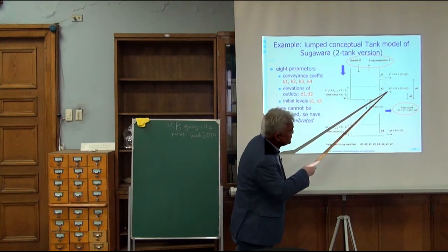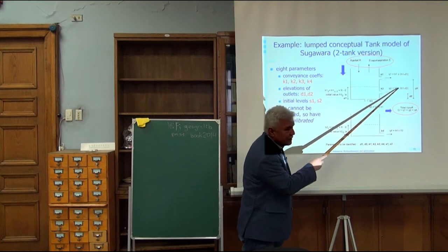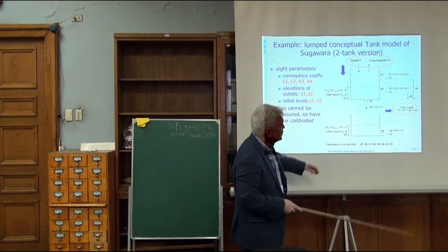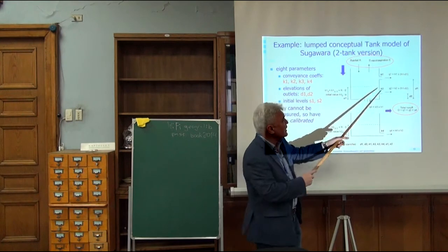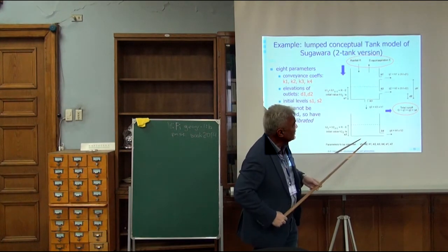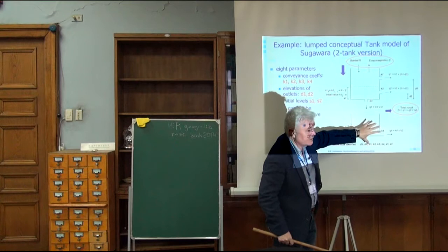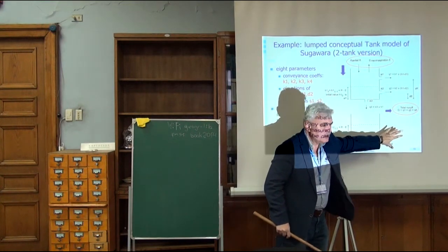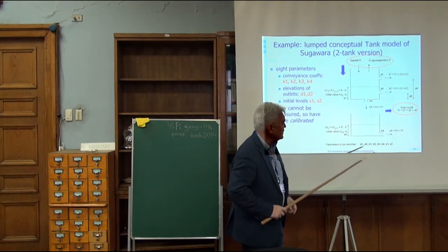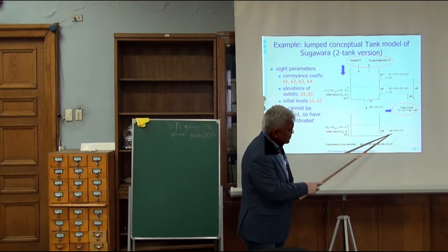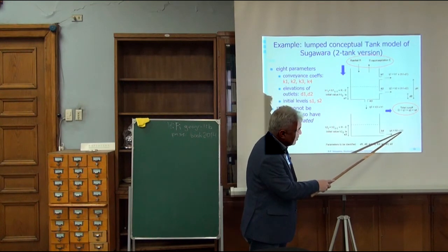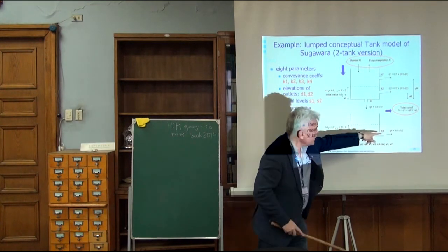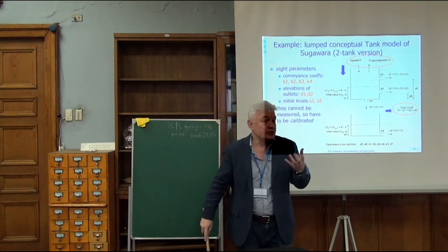flow. And you see these equations for runoff here are linear. Okay, it's all linear equations. You can say linear reservoir, but there are two outlets, so it becomes piecewise linear as the water level goes up. So this is the initial water level. And then it percolates somewhere to sort of base flow or groundwater flow, whatever you call it, an intermediate tank, which also is a linear reservoir with the linear dependency of flow on level. So H is the water level in this tank, or soil moisture, you can say.